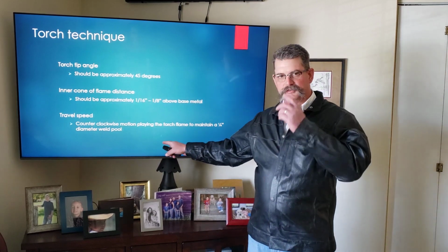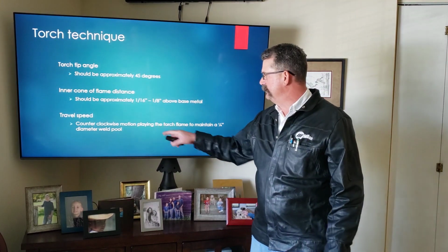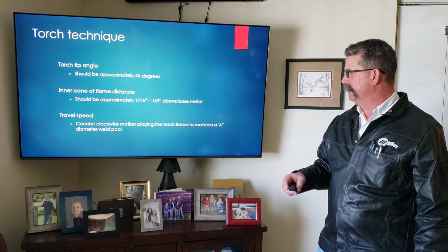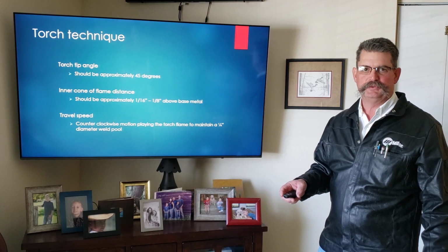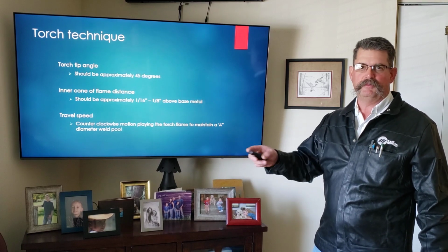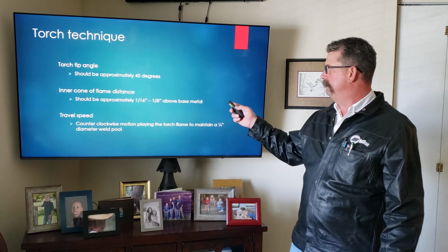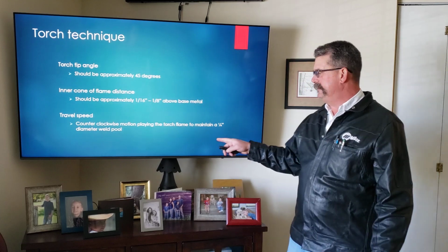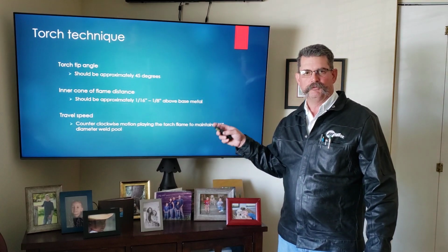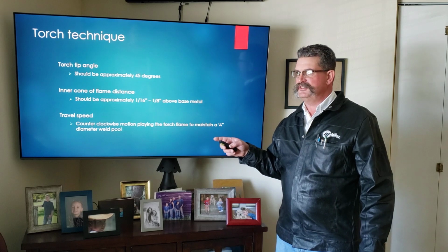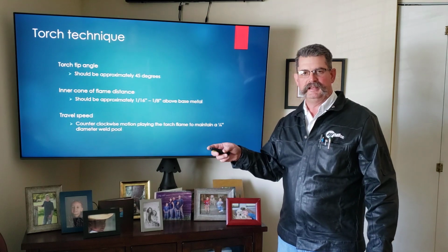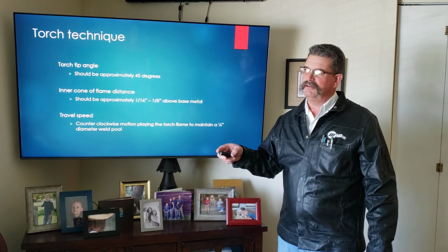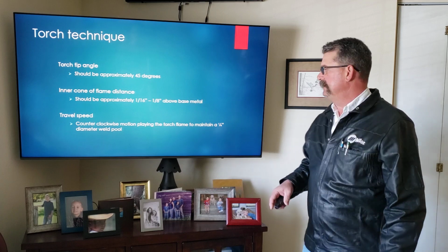And then the third factor, which is very important, is travel speed. In the welding process for a right-handed individual, you'll develop the counterclockwise motion, the practice of maintaining that torch tip angle and the inner cone distance, and then basically your travel from right to left, in that it's just opposite from writing. If you're a right-handed person, you need to develop that torch technique traveling counterclockwise from right to left.